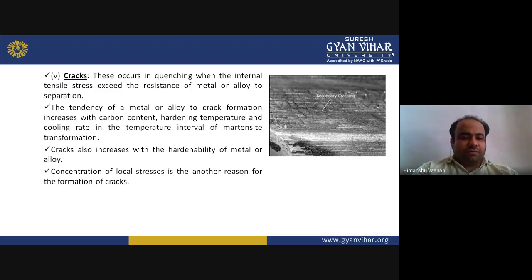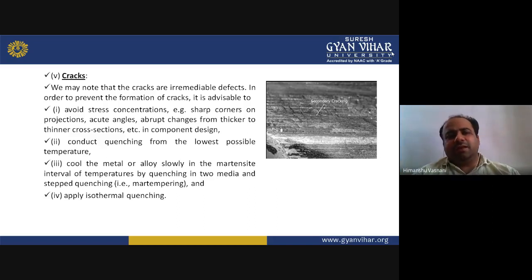The concentration of local stress is another reason for the formation of cracks. We had discussed this earlier also, so not a big deal. We note that cracks are irremediable defects, obviously, so we need to prevent their formation. It is advisable to avoid stress concentration, that is, sharp corners on projections, acute angles, and abrupt changes from thicker to thinner cross section at the time of component design.